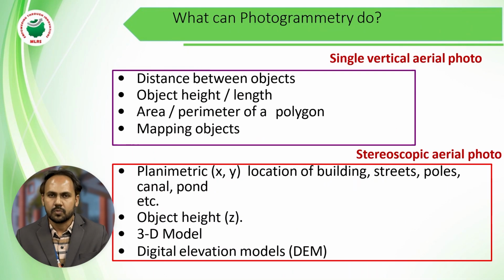So what can photogrammetry do? With the help of a single vertical photograph, we can get the distance between two objects, two buildings or two structures. Object height or length, any one parameter, can be decided from a single vertical photograph. Area and perimeter of a polygon too. If we would like to execute any project, or construct any building in an area, what is the area of that particular site, what is the area of that particular building, etc. All this data we can analyze from a single vertical photograph, and mapping can also be done with the help of a single vertical photograph. But with the help of a stereoscopic aerial photograph...